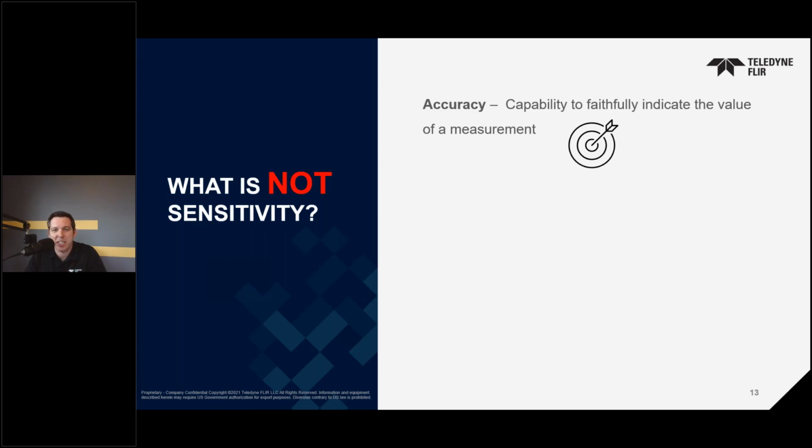The specification is going to be the result of a widely used uncertainty analysis technique called root sum squares, or RSS. The idea is that you calculate the partial errors for each variable of the temperature measurement equation, square each of those error terms, add them together, and take the square root. Those partial errors can result from several variables, including the surface emissivity of the target, reflected ambient temperature if you've got a low emissivity target, transmittance, atmospheric temperature, and so on.